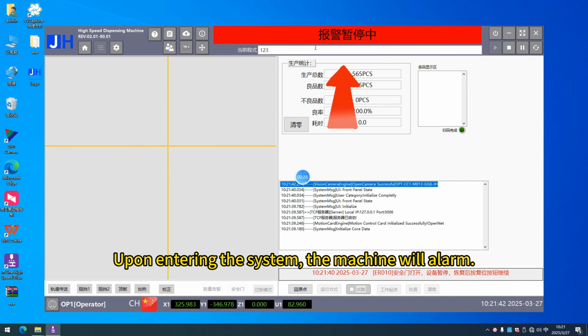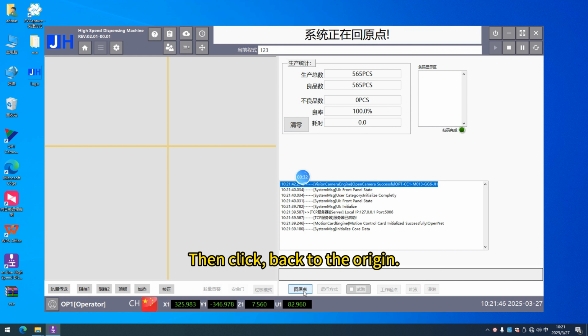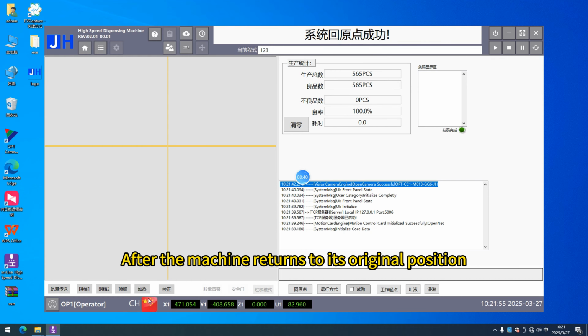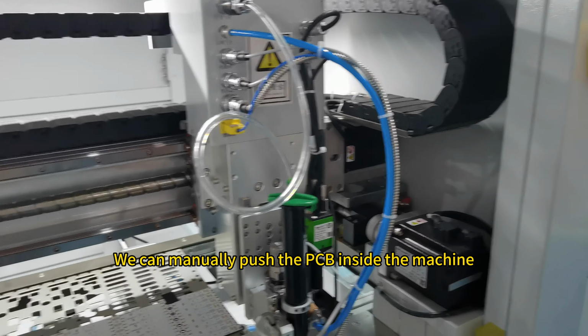Upon entering the system, the machine will alarm. Then click back to the origin. At this point, the X, Y, Z axes of the machine will return to the home position. After the machine returns to its original position, we can manually push the PCB inside the machine.